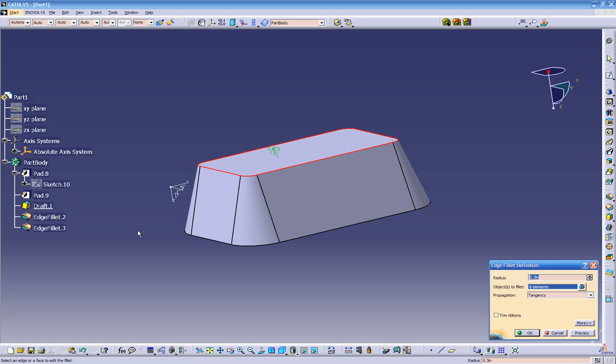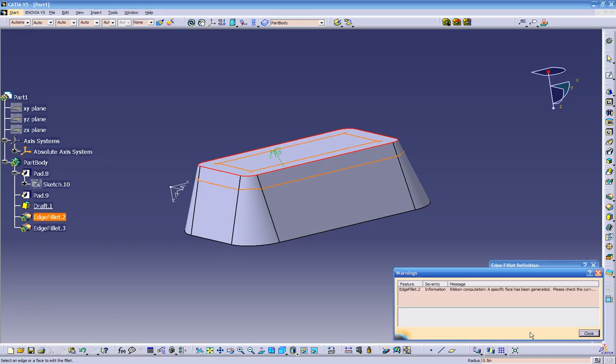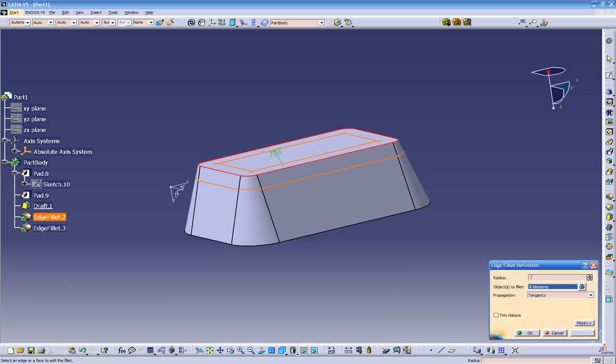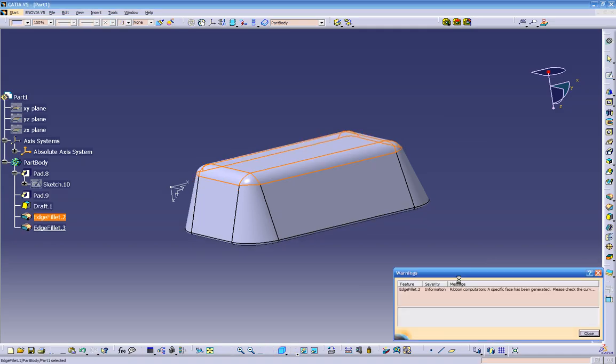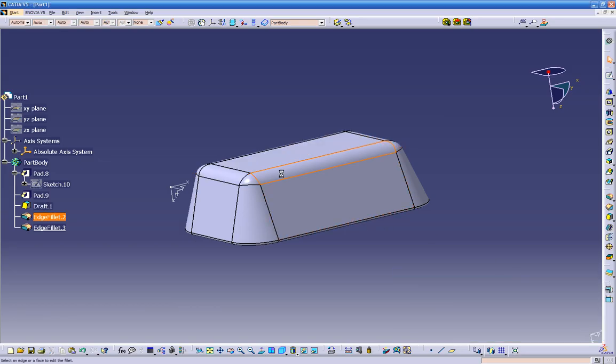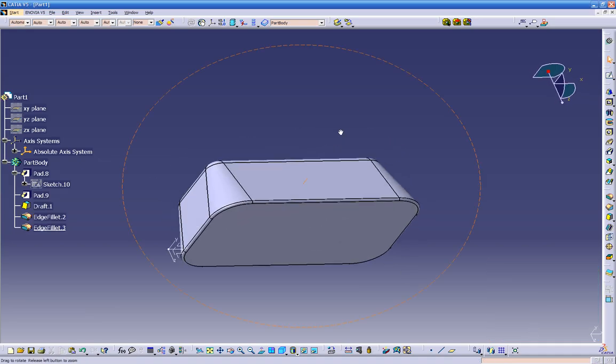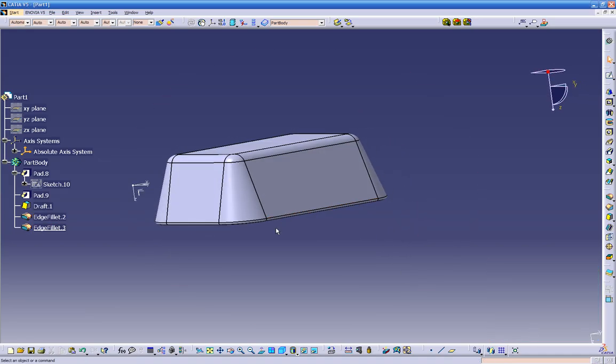Double click on the fillet, same thing, we can change it to 1/2 inch. Let's do a preview. Oh, it's just too big, so it doesn't like that because it overlaps. So let's make it a little smaller. Let's make it 350. That's still a little bit too big, so let's make it 300. Actually, let's get a little smaller, 250. Click OK.